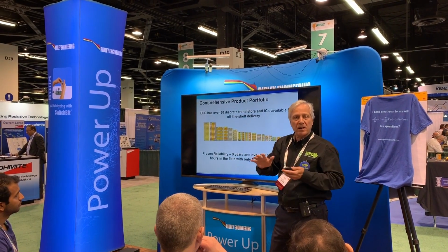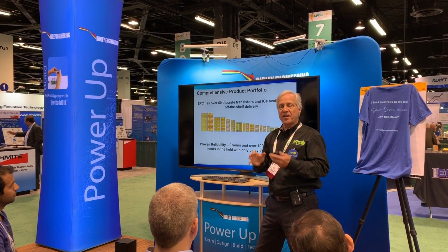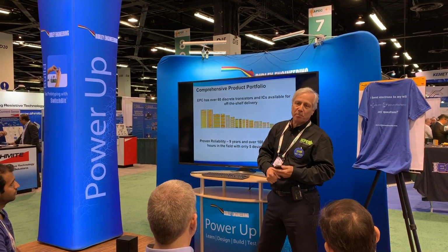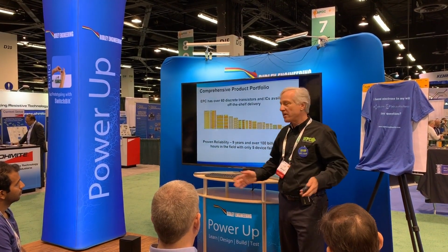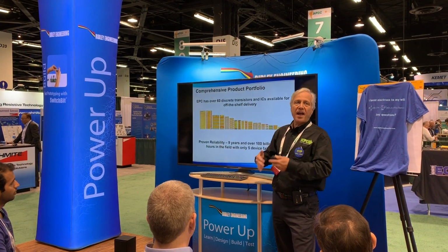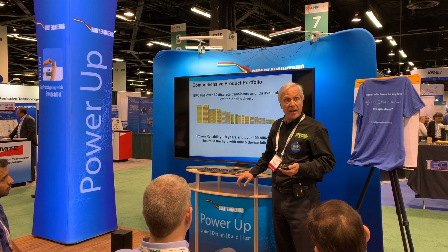There are thermomechanical interfaces, dissimilar materials, all sorts of bad stuff going on in there, wire bonds that are welded to your part, and everything's moving around all the time with moisture getting in and out. Our parts are glass passivated, and they got none of that nonsense. And therefore, there's really not much to fail.